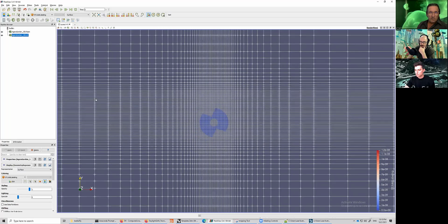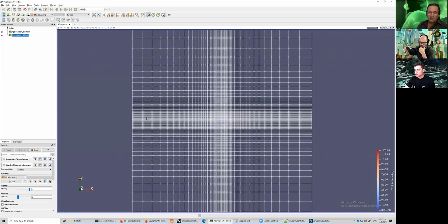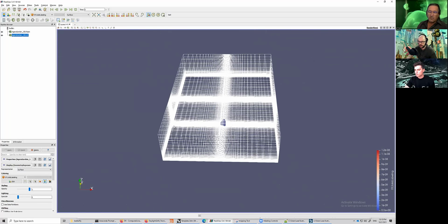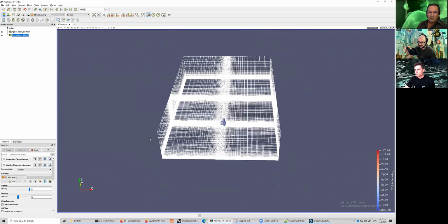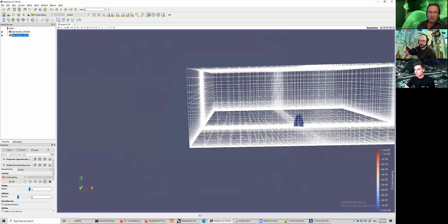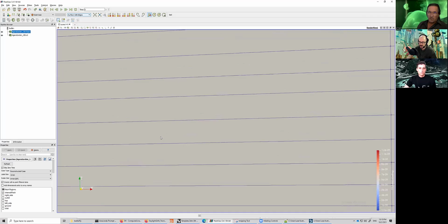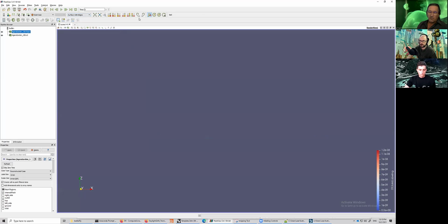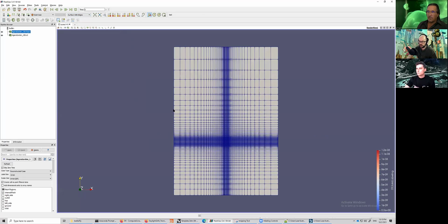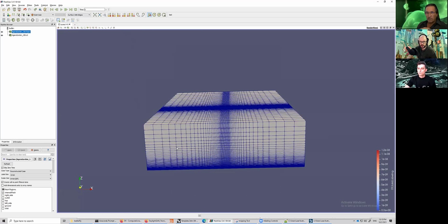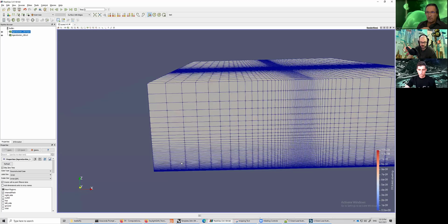And the other thing that Butterfly automatically does is a sort of best practice on the Z, which is quite nice, I think. And you can see it here. If I do a surface with edges here, you will see it. So Butterfly also generates a mesh. This is a bit fortunate if you do outdoor studies, a bit unfortunate if you want to do other stuff, because this is made for almost comfort studies, right?